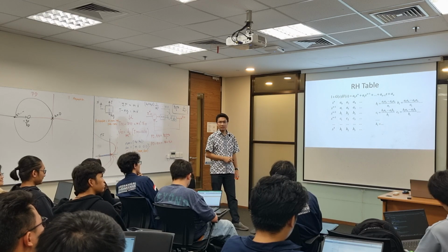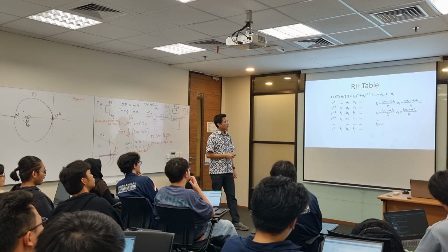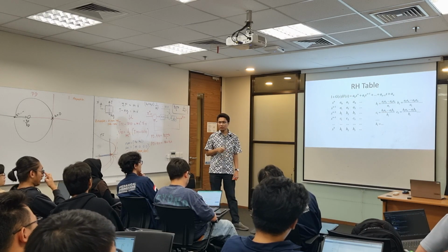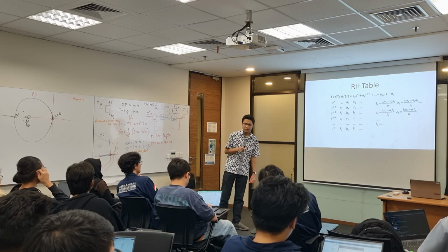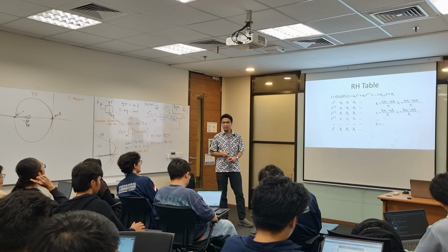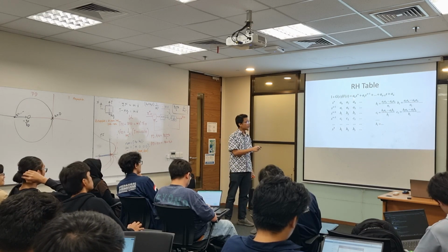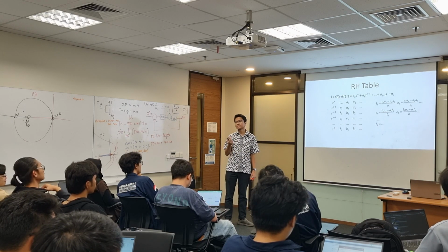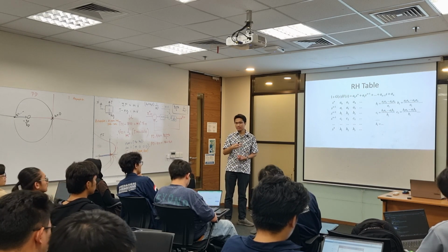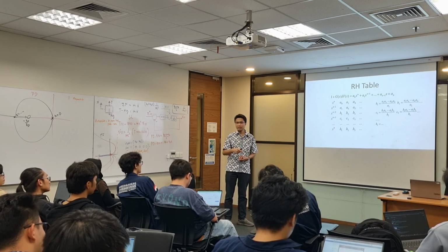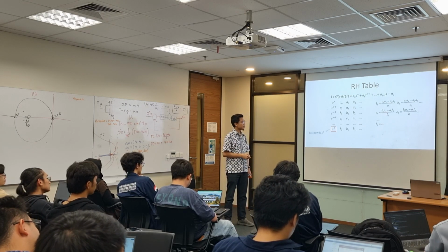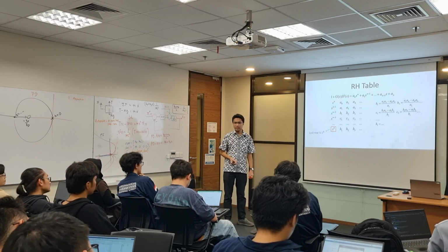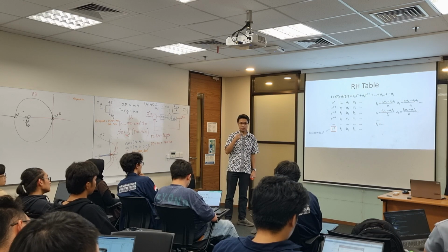Another review is about the Routh table. You make a table out from the polynomial that you want to test. If you want to test the stability, then the polynomial that you take here is the characteristic equation. It's from the denominator, where you will find the poles of the transfer function. The last row of your Routh table is always s to the power of 0.